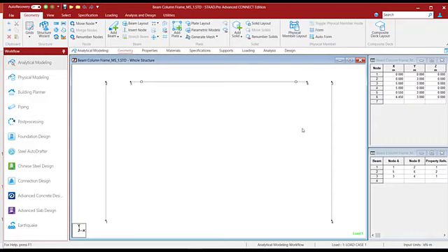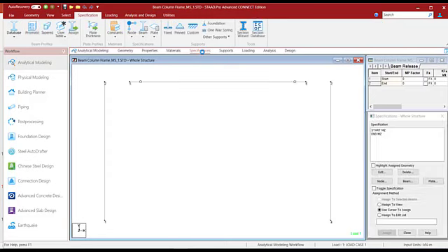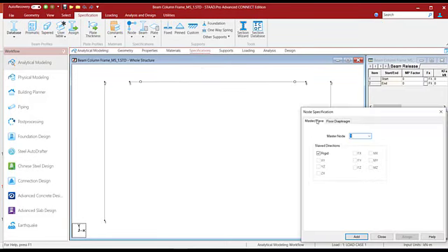Finally, I'd like to quickly show you how to define master-slave. Now that we have understood the implications of using master-slave, just a quick demonstration on how you could define a master-slave in this particular model. So you need to go to the specification option and click on the node, and the first option is master-slave. So you have to select the master node. In our case, let us select the master node as node number 2.